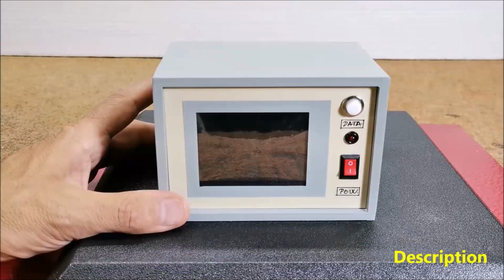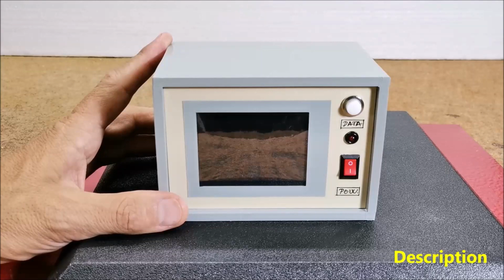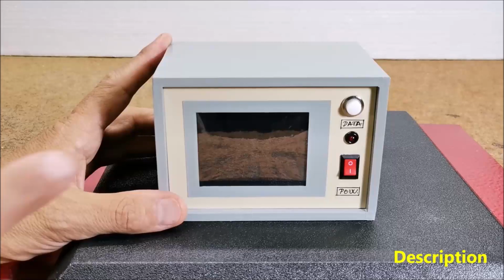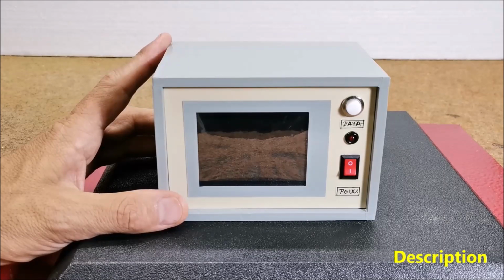The device that is presented this time works independently, so it is completely flexible in terms of installation location, size, as well as the cost of the entire device. The results are displayed on the 2.8-inch TFT LCD display, but also, thanks to the use of the ESP8266 Wi-Fi module, are sent to a Windows PC running a small server application to log the data on a chart, to be viewed in the application itself, or in a web browser, either on the PC or over the internet. So the PC needs to have a static IP address set up in its network properties settings.